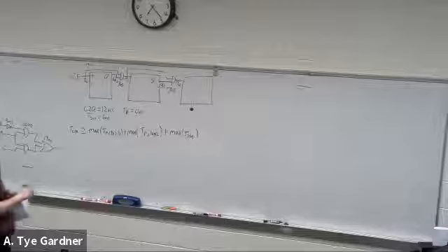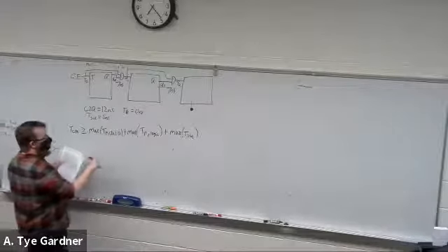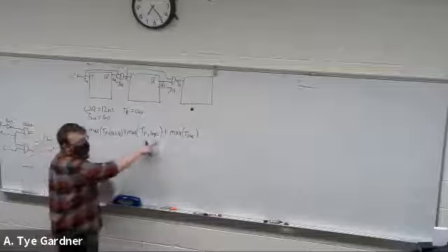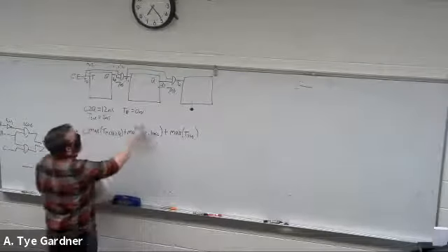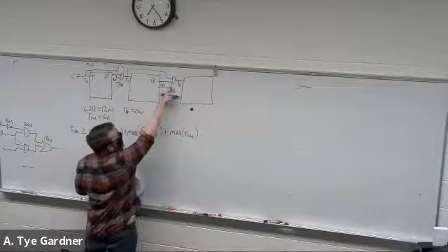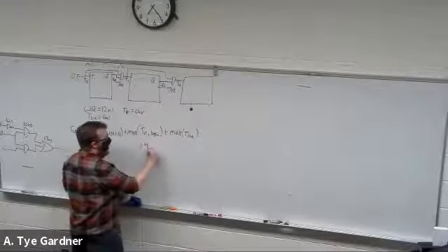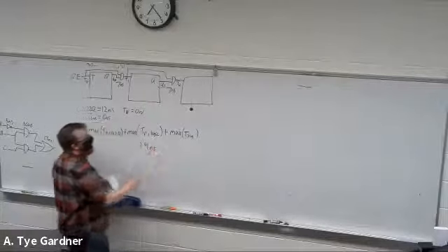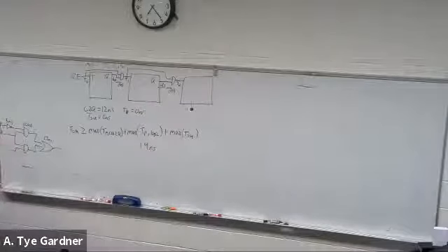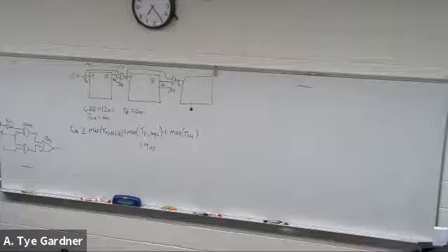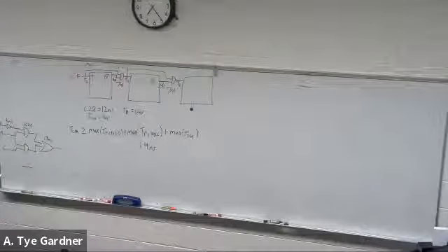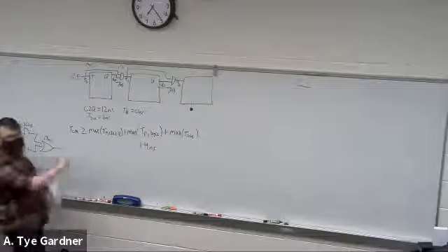So what are we looking at? Well, we have this time delay of the logic that's going 7 nanoseconds plus 7 nanoseconds. So that is our longest logic delay. And then I said that my clock to Q was 12 nanoseconds.